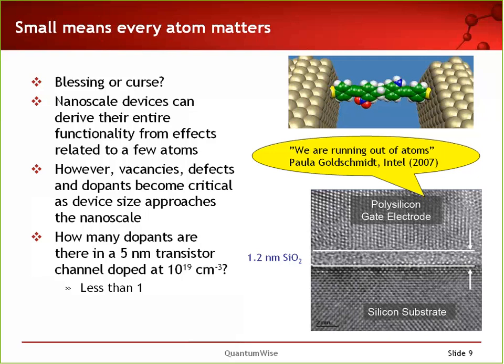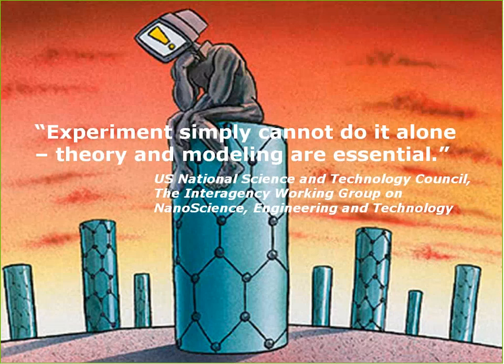Now, this was solved by the introduction of high-K dielectrics, which are actually thicker than 1.2 nanometers. They're usually in the range of 3 nanometers. But if you really want to dope the channel and have free carriers thanks to that, then at these short channel lengths, that might not actually be an option. And I will come back a little bit to that later on.